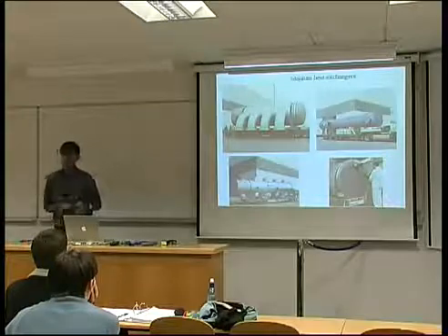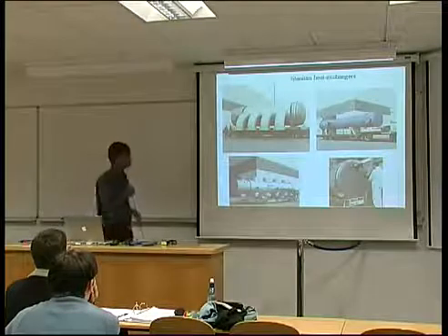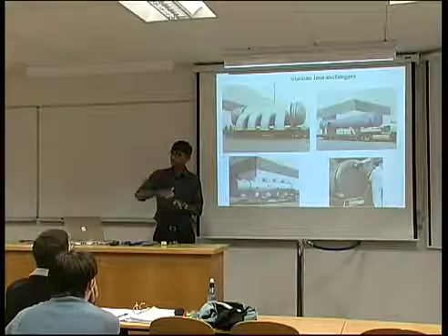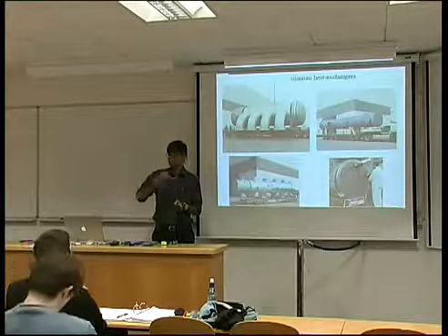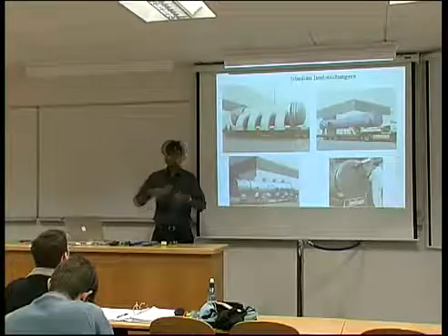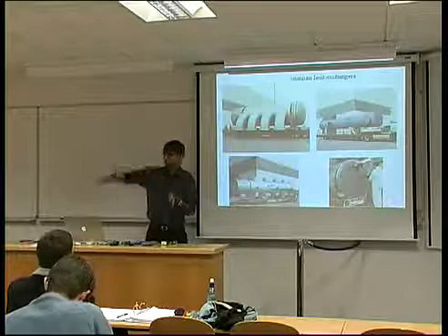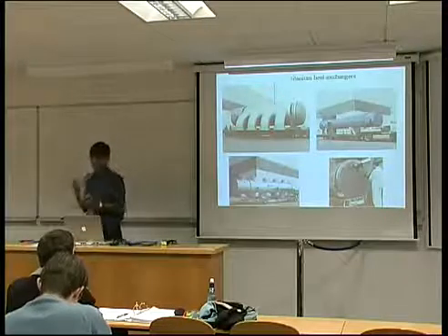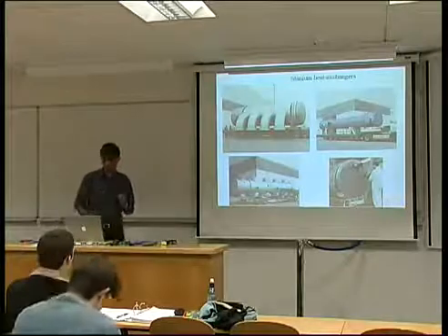The steel gives the supporting strength and structure to the chemical plant. And the titanium will be bonded to the steel by explosion bonding, for example. So you have a charge detonated which propagates, and solid state bonding of titanium to the steel. So a large quantity of titanium is used in the chemicals industry.